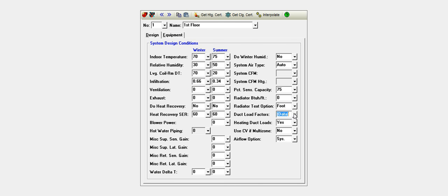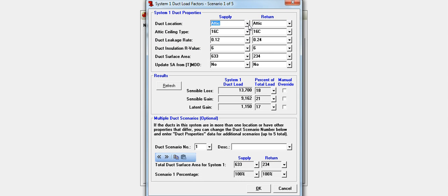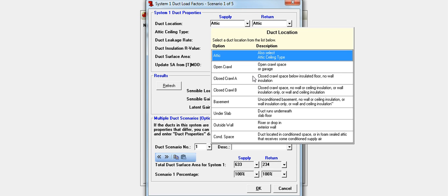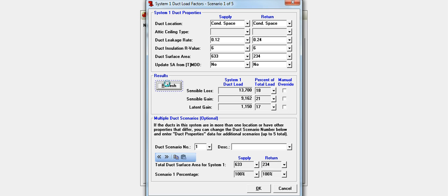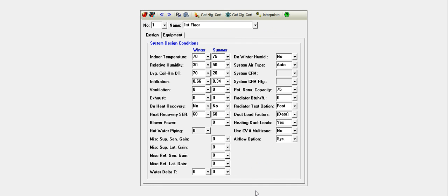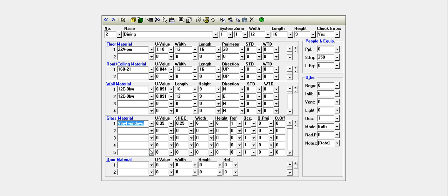But definitely we're going to move the duct away from the vented attic. So we're going to put the duct inside a conditioned space, because this is actually our greatest benefit, even better than the windows. So let me change all the windows throughout the house, and then when we come back, we'll look.